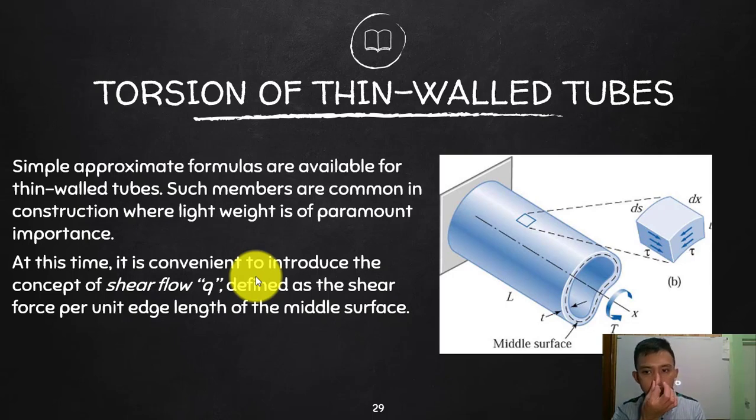Okay, and at the same time, why is it that we will try to make use of thin wall? Why is it that we will not use a solid, which is a smaller size? Because again, as I've said, the farther the point from the point of rotation or center of rotation, the bigger the stress on that part.